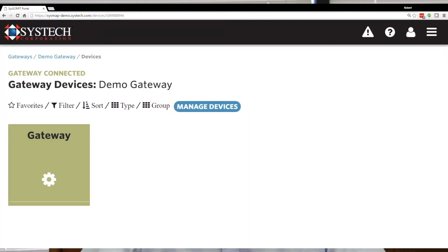It's easy to add and remove external devices on the gateway. For example, to add an Aeon Labs door contact sensor, follow these instructions. For Z-Wave devices, it's usually best to remove them first in case they were associated with some other Z-Wave network. So, to remove a Z-Wave device from its previous network, put the gateway into the Z-Wave remove mode. To do this, select the Devices button of the gateway. This will bring you to a screen showing the devices currently attached to that gateway.